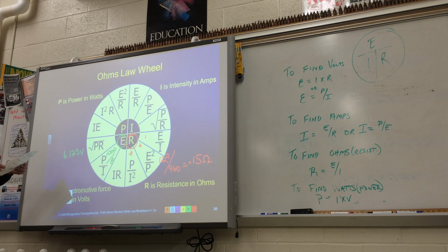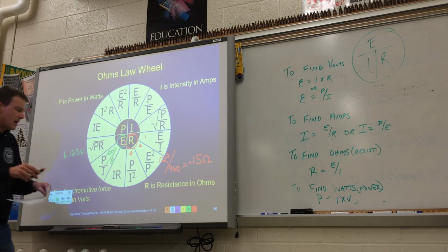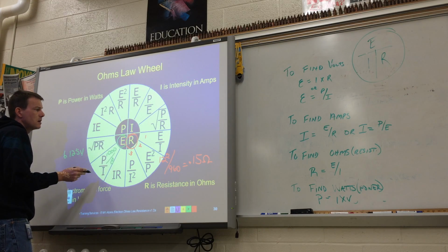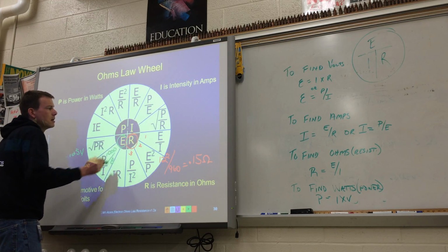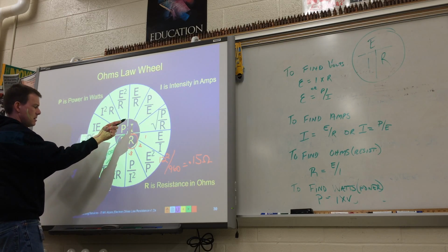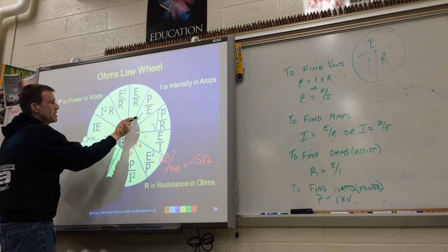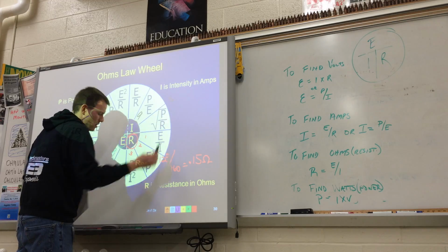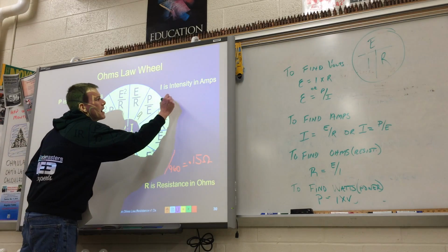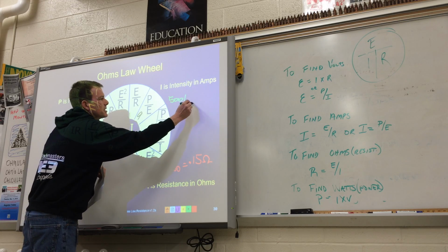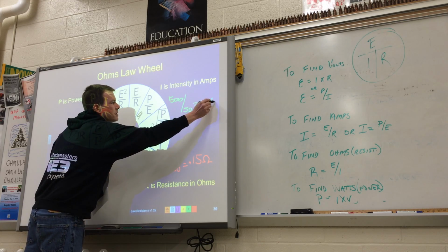So number 8. What are you given? You're given power and what? And you're trying to find what? Current. Which one's current? P-E-I-R? All right. And what do we have? Power and voltage, which is this one here. So it's going to be power, 500. It's kind of hard to read that. I'm going to go back to green up here. 500 divided by what? 50. 50 gives us 10 amps.